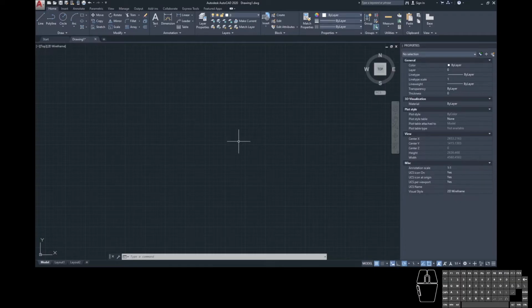So when dynamic input is on, what you'll find is that your command bar is associated with your cursor, and there are a few more options when we go to draw a line. So we're going to engage our line tool by typing L and then enter. It's asking us to specify a first point, and it's asking us near with the cursor, and it's still asking us down here in the command bar.